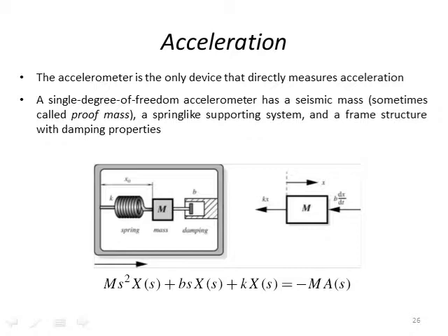When this frame, this boxed region, changes, typically this mass is already vibrating. And the vibration is going to be a function of the mass, the damping, and the spring. When an acceleration happens, it's going to change the resonant frequency of the vibration of this mass, spring, damper system.